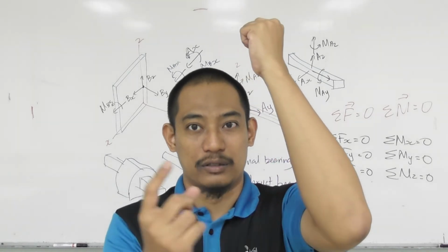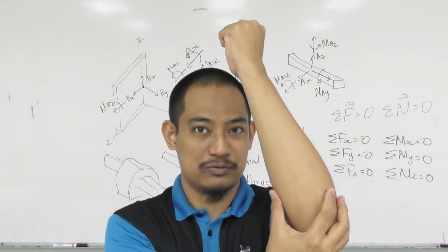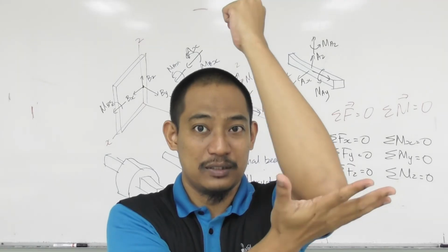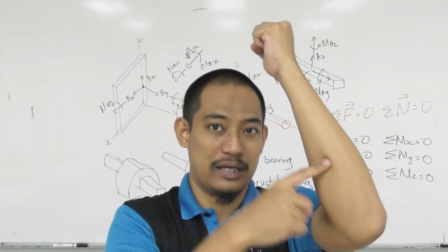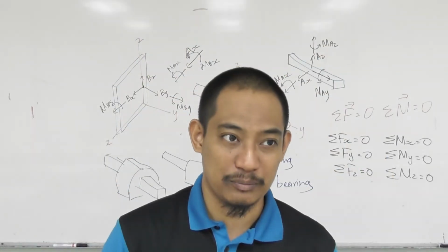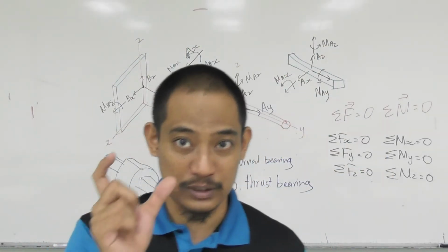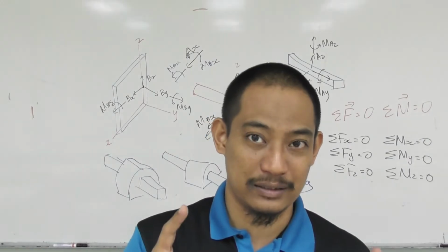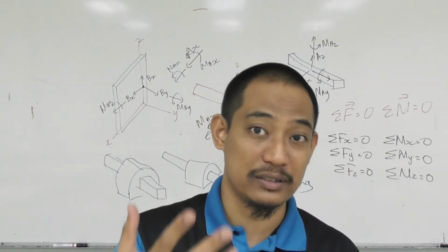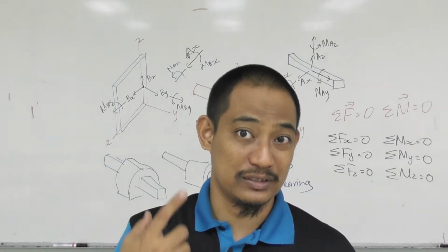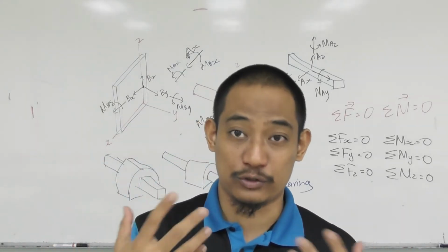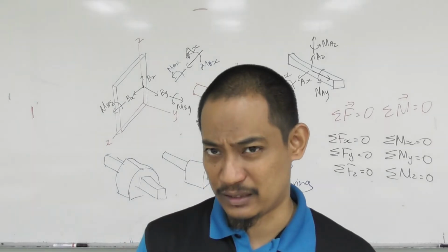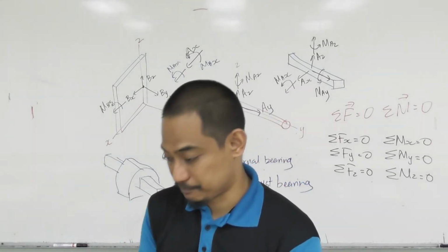So you have to understand, when this changes from ball and socket to fixed, it changes from 3 unknowns to 6 unknowns here, and added to the other unknowns, the number of unknowns is more, hence you can use that phrase. Now it is statically indeterminate, meaning you cannot determine the force using statics, because in using statics we only have this equation here, and hence you cannot solve. So that's an understanding question that can be asked in the exam. Alright.